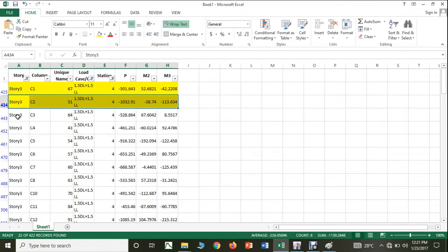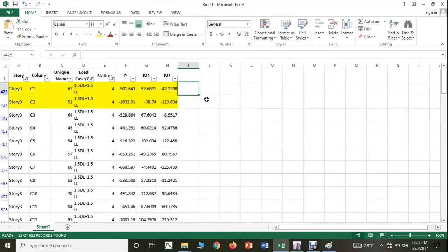We will do the same for the next problem. So I can write that this I can design as biaxial loaded, so I can write BI. This also I am supposed to design as BI. This I can design as uniaxial, I can write UI.